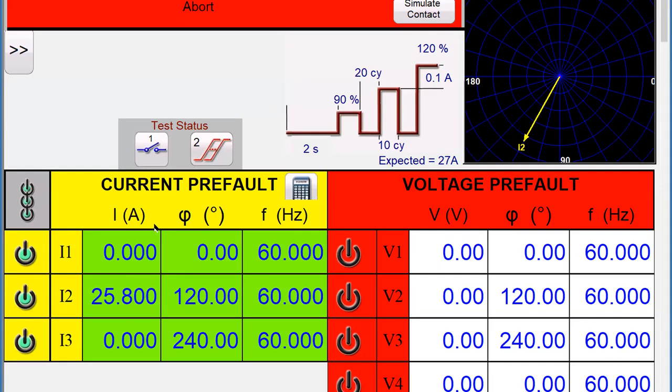And again, you're seeing here, see how the increment in the pulse? As I look at 3, this will be my C phase. You'll notice that this is actually pulsing. So it looks like it's ramping, it's incrementing up the value, but actually what it's doing is pulsing it on for your 10 cycle delay on and 20 cycles off. So each one is actually working.